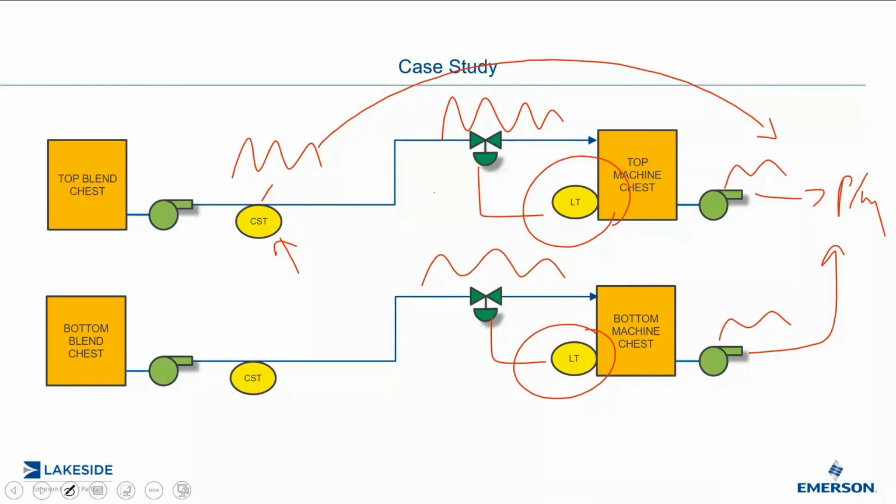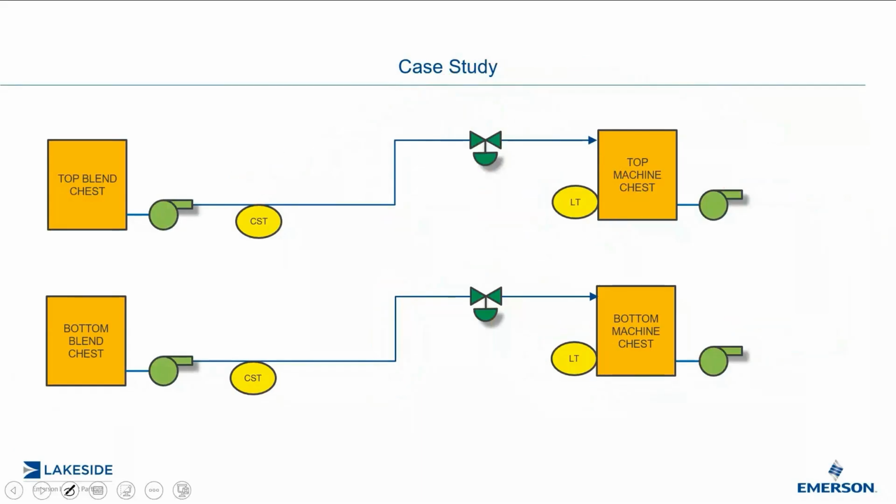Inside here, I didn't really show it, but in between there's a very flow-sensitive piece of equipment called refiners. A refiner puts the pulp slurry between two counter-rotating plates, and it fibrillates the fiber. Each paper fiber actually has little hairs, and this fibrillates it, essentially giving it an afro. So when you put it on the paper machine, all those fibrils intertwine, making the paper stronger. All this is here to make sure we understand the process.